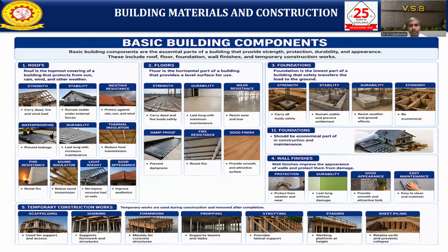Now the next component is temporary construction work. Temporary works are used during construction and removed after completion. The main one is scaffolding. Scaffolding is mainly used for support and access. Shoring supports the formwork and the structure. Formwork molds the concrete of the structure.